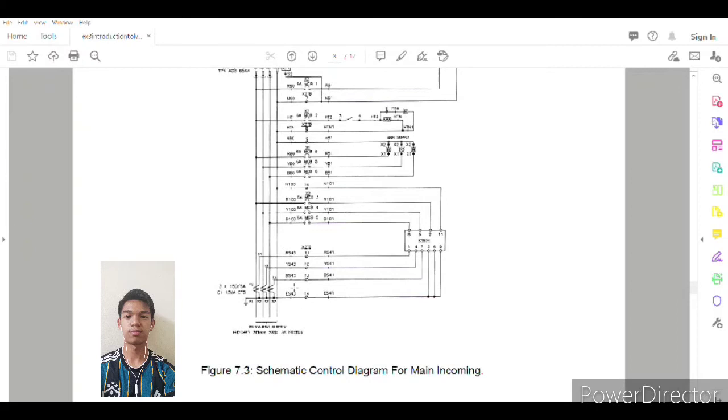So the schematic diagram is the AC supply. It means the 3-phase is taken down to a single phase diagram. How do we know this is the 3-phase diagram? As you can see, the labeling RYB means red, yellow, and blue. The RS, YS, and BS are also the same, and the ES is the earth, which is neutral, connected to the ground.